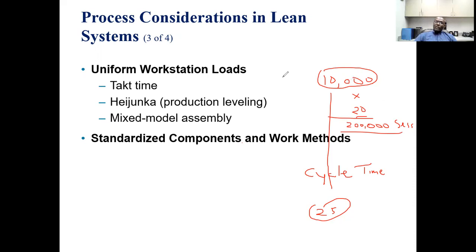Okay, and to accomplish that, we look at the uniform workstation loading, and this has to do with how much work does every workstation get, and how can we balance that out so that we don't have some employees working way much harder than others. How do we bring a sense of balance when different processes usually take different amounts of time. Okay, so our Heijunka talks to how do we achieve that uniform workstation loading in a system with multiple workstations producing different components of one entire product.